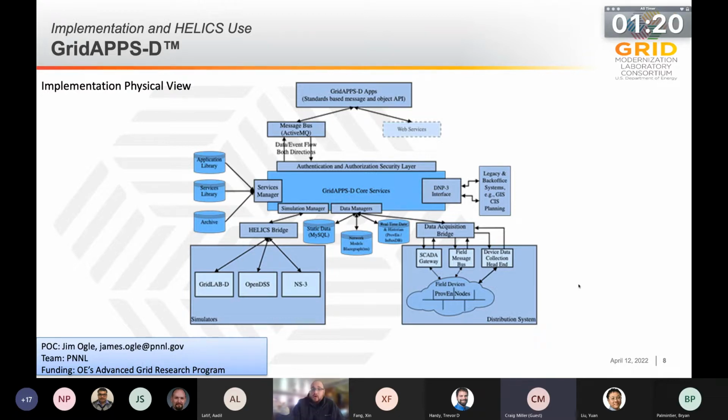So to the vendor applications, it doesn't really matter. It's abstracting away the actual SCADA connections so that they don't have to deal with that. And the managers inside there are the ones hooked up to the real world SCADA and translating that to get the data into the standard SIM format that all the applications are expecting.